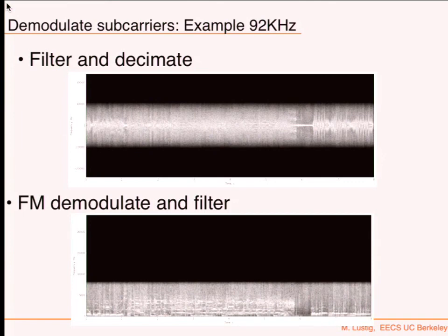First of all, I think I captured something that was relatively noisy up in the beginning. The other thing is that the high frequencies in FM radio are noisier. It's the fact that I take a derivative operation to demodulate, which amplifies the noise in the high frequencies. So that's what they actually do in FM: they pre-compensate for some of those. They have a pre-compensation filter that amplifies the high frequencies before they FM modulate, and then you have to tone it down after you demodulate.